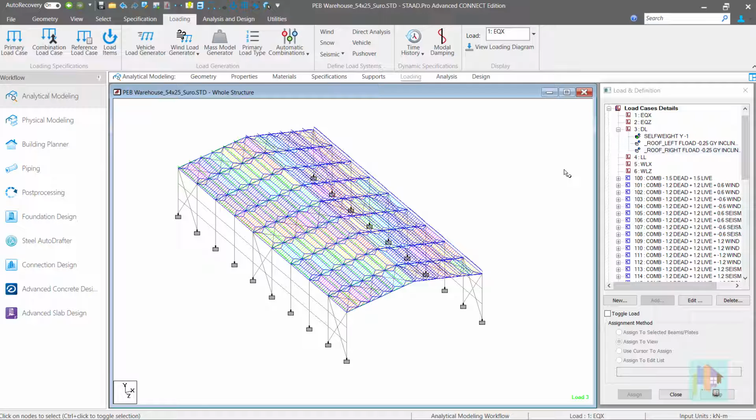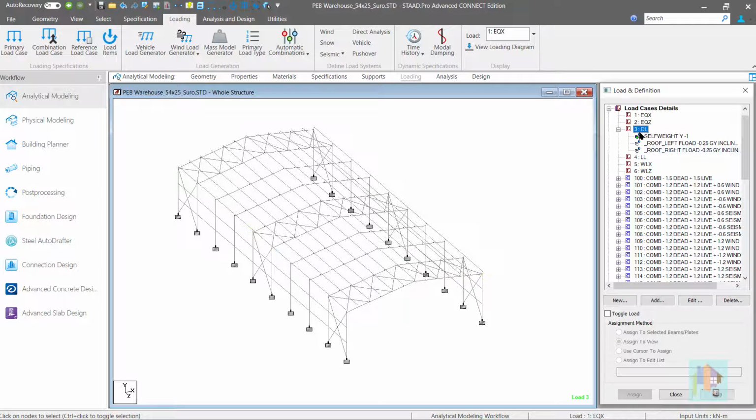Also, we can apply load on part of the roof. If there is any area with additional load, like a few solar panels or transparent sheet with separate unit weight, we can create a new floor group and use that to apply floor load on that portion.